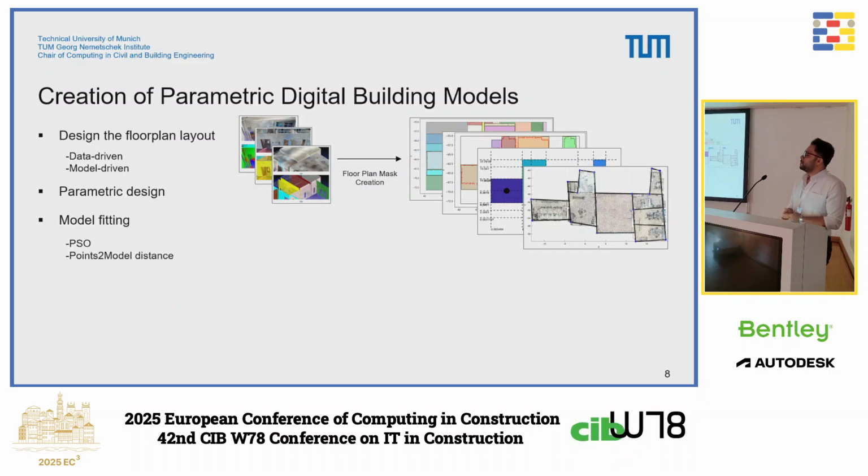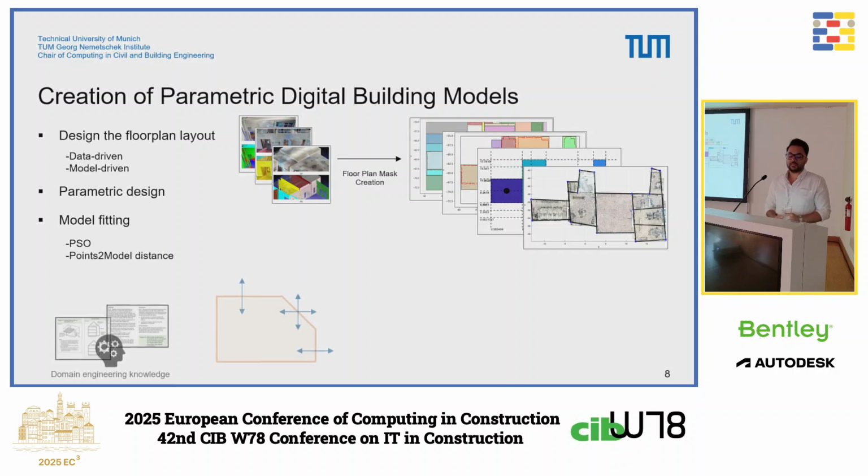But actually, these methods depend on the quality of the data. In the presence of noise, gaps, and over-segmentation, they may result in a floor plan mask with inconsistent geometry. What we have proposed here is to use a global optimization through parametric model fitting.